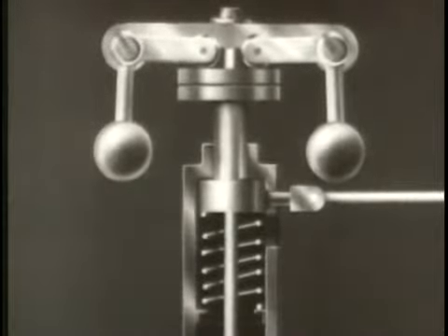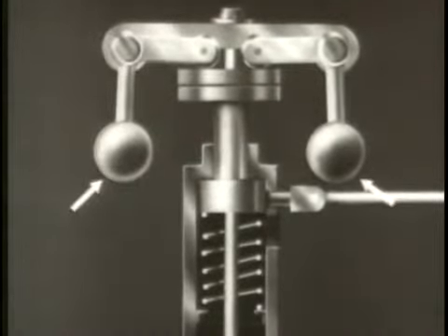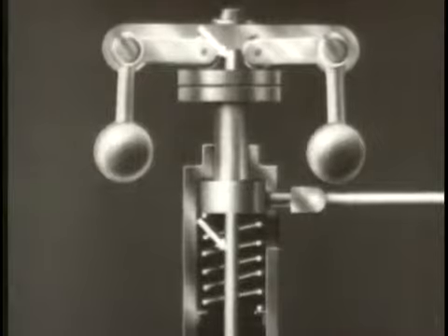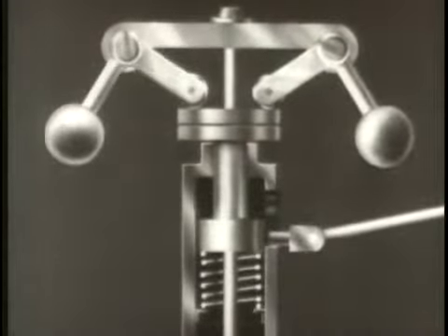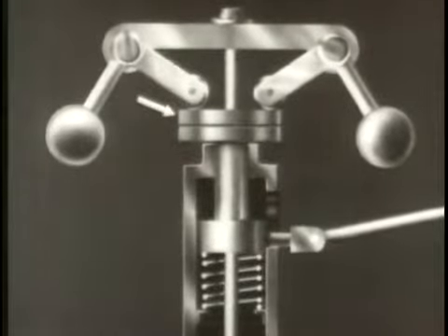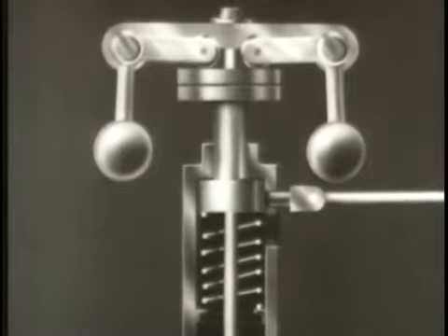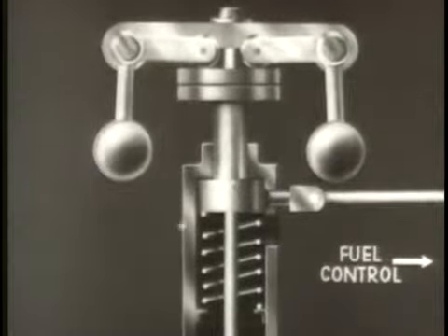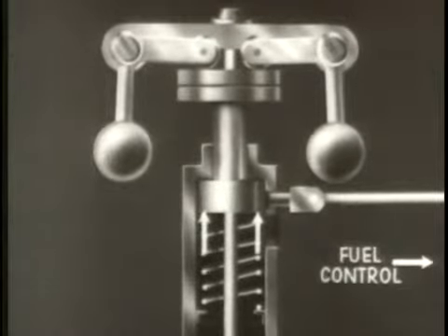One type of governor is the overspeed governor. It acts merely as a safety device and keeps the engine from overspeeding or racing. The basis of the overspeed governor is a pair of flyweights mounted on the drive shaft. The outward motion of the flyweights is transmitted to a collar which slides on the shaft. The movement of this collar actuates a linkage to the fuel pump controls. A spring presses upward against the collar.